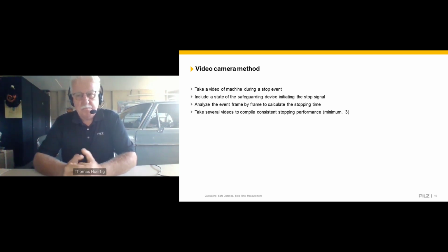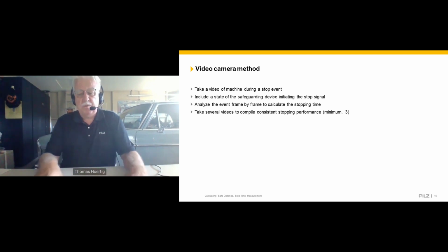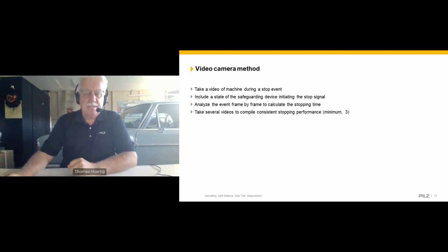This is a more practical approach, very good for estimation and also for confirmation. But also, please have a look at the respective machinery C, as in Charlie, type standard for the machines, because those C standards, those ANSI standards or EN standards or international standards, give you information on the specific type of machines and give you formulas and guidance on how to make this fit your application needs.